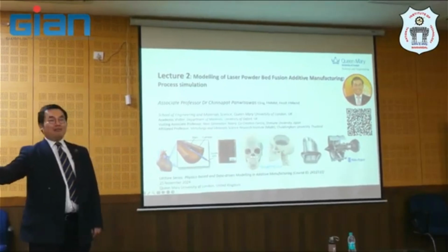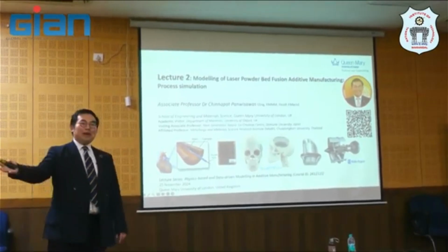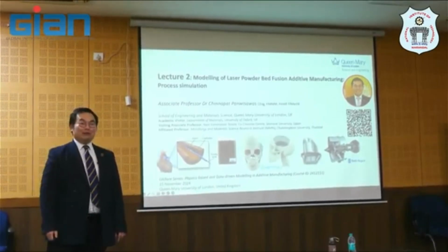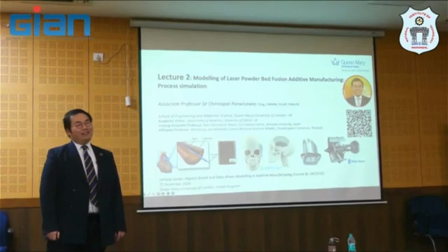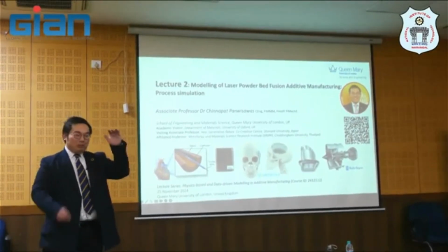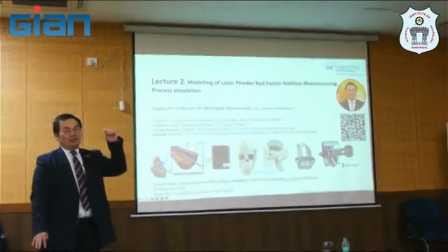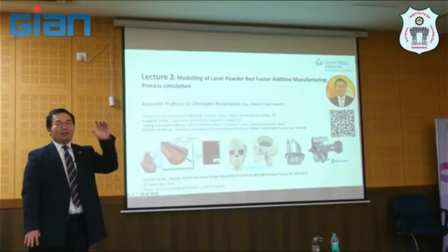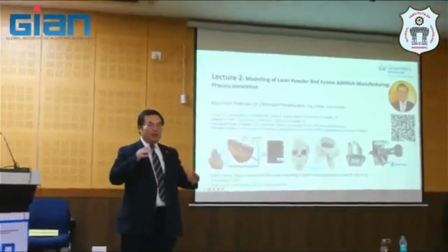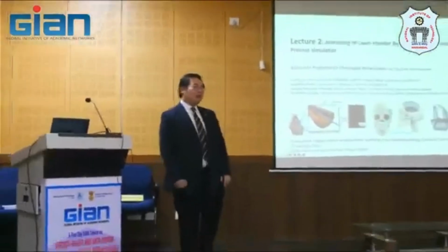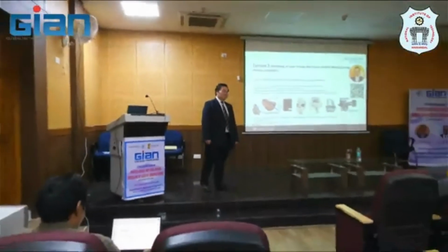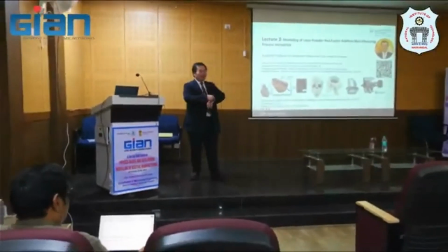Okay, I have, for example, a high entropy alloy which outweighs the performance of CMSX, which I don't think anyone is yet trying, because if you're good in strength, you will not be good in oxidation, and this cannot compromise creep resistance. So that's why CMSX-4 is still the better choice for them. Anyway, we can talk more on that.